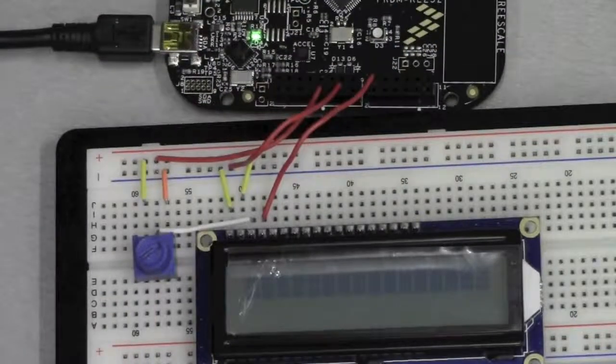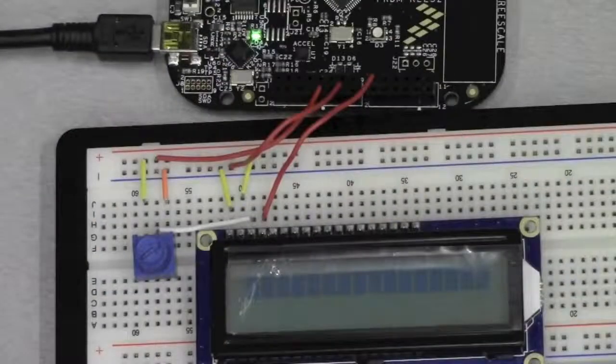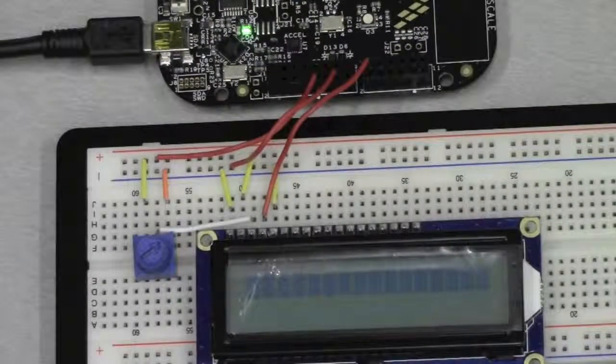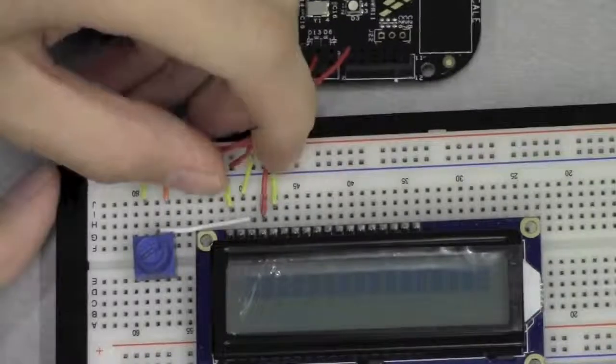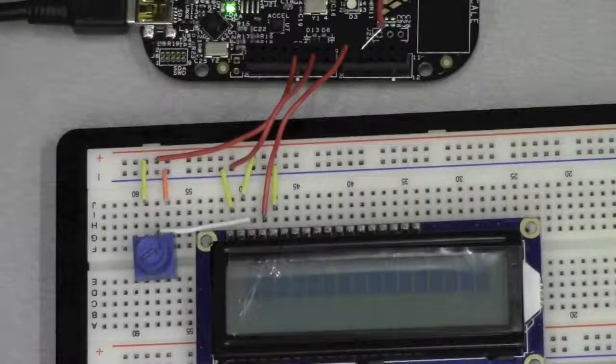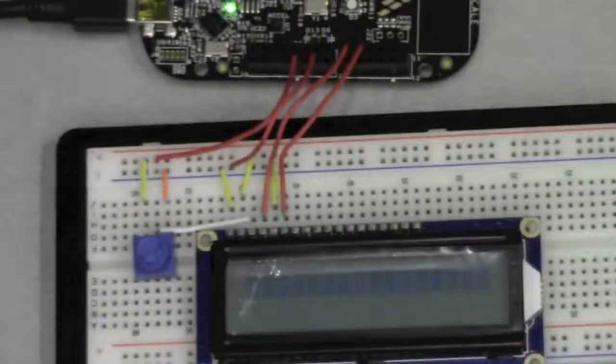The next one is read write, which we're not going to be using. Instead, we're going to connect this to 0 volts. Okay, now that we have that connected to 0 volts, we'll look at the next one. The next pin is enable, which is pin 6. That's going to be connected to another digital pin, so we're going to connect it to the top left right here. Okay, that's the next one.